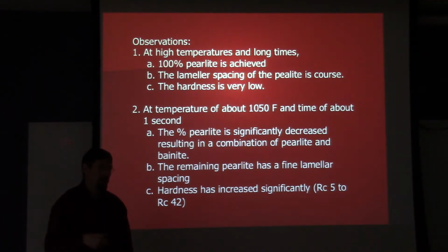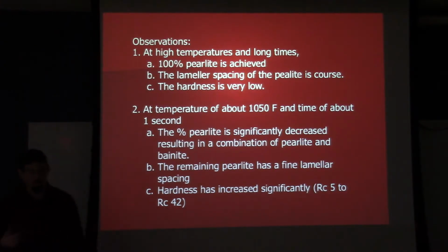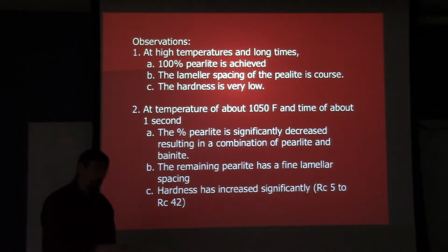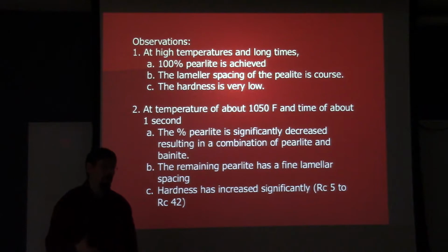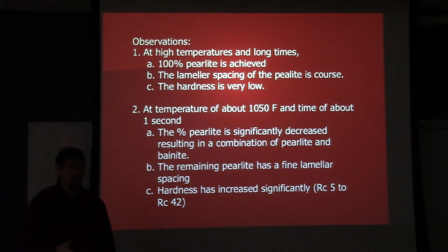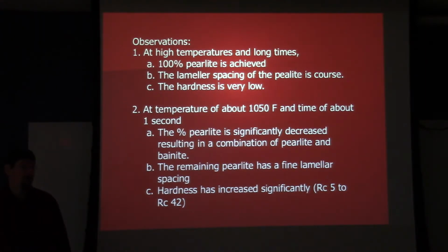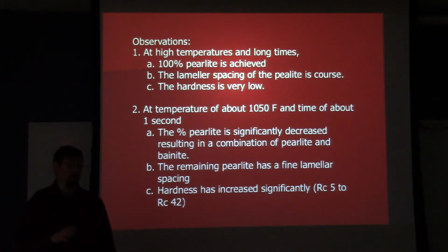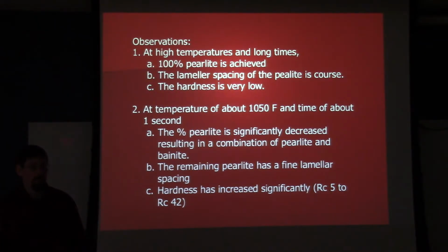And so that's a problem. But on the other hand, if you have a uniform bainite structure, you can have an extremely tough item, whatever it is that you're making. So as with everything in metallurgy, it really depends on what you're trying to accomplish and what you're able to accomplish given the chemistry and cooling resources you have available.